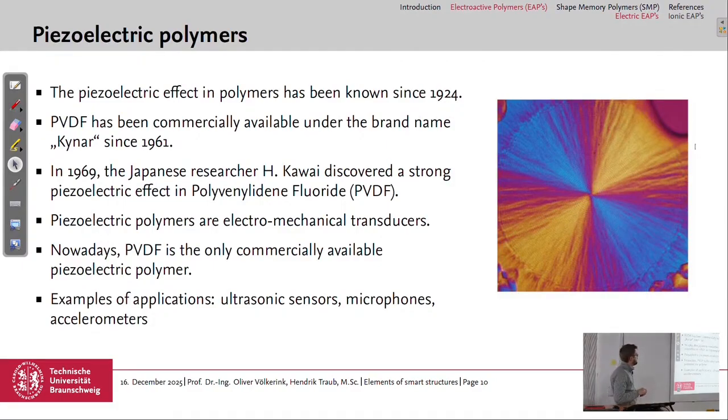And well, PVDF is a material which has piezoelectric properties, at least in a certain state, like the piezoceramics, where you need this special lattice structure, so not the cubic lattice, but a rhombohedral, for example. And also PVDF has to be in a certain phase to have piezoelectric properties. We will have a look on that.